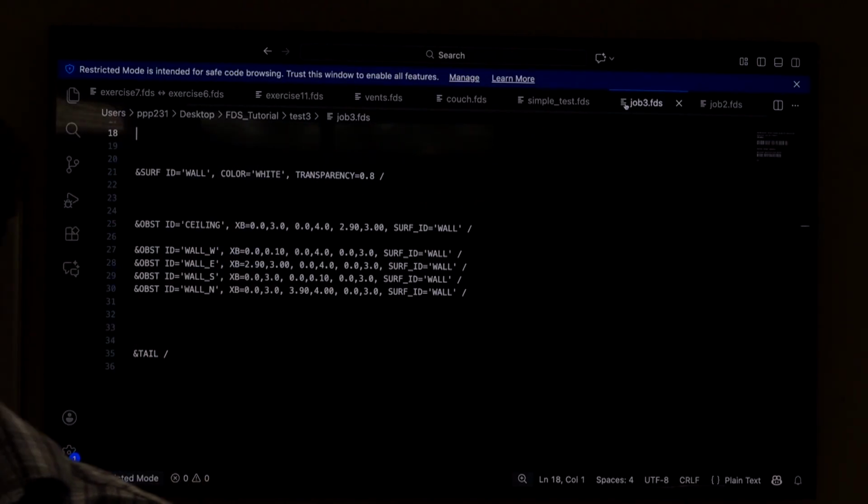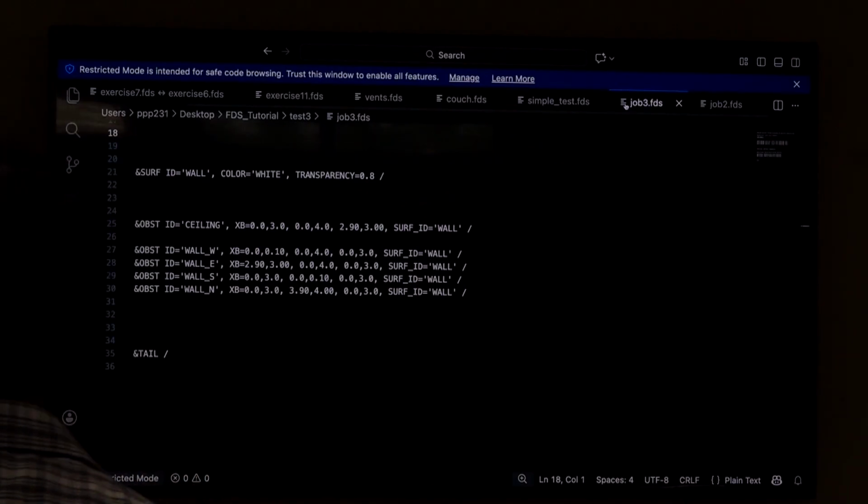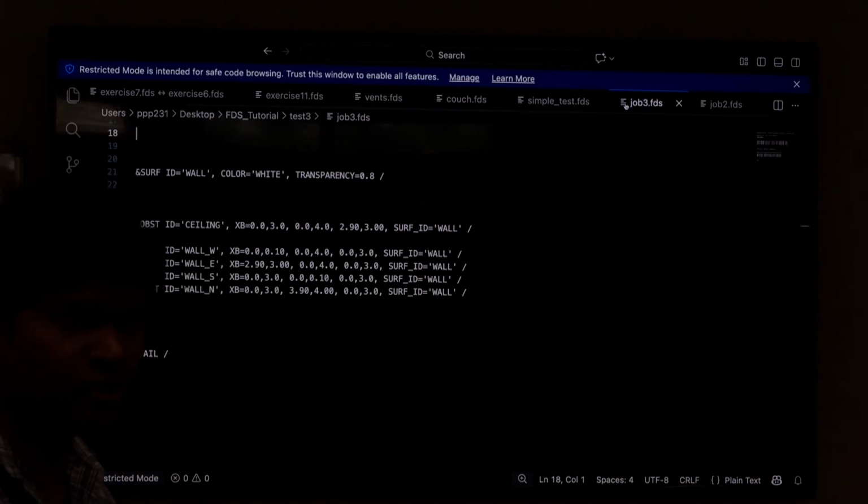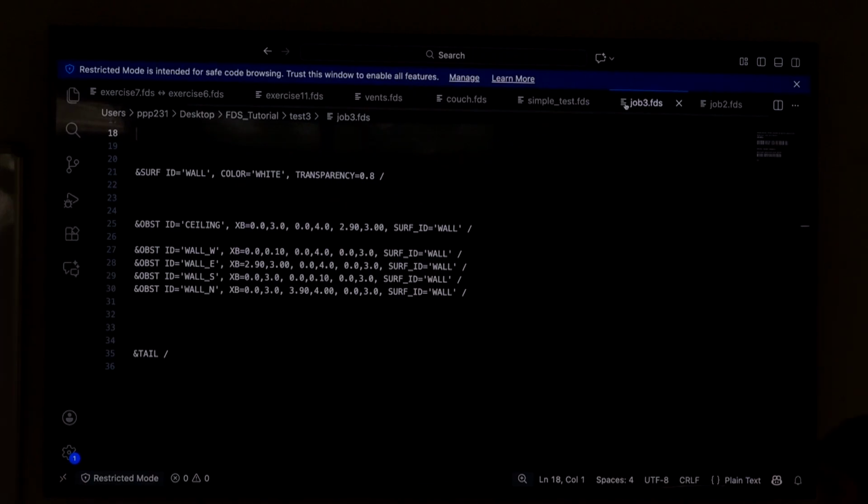The thing is, when you are running the smoke view file, just to make sure your geometry is as per your expectation, don't wait for your simulation to complete, until like 60 seconds. You don't need to, because this is not your final simulation.